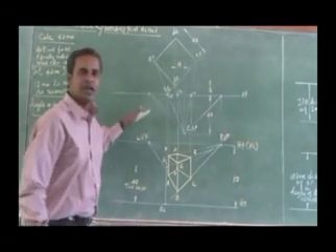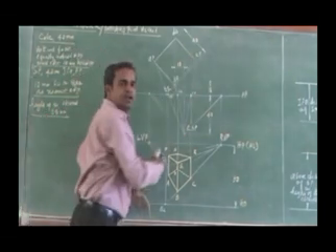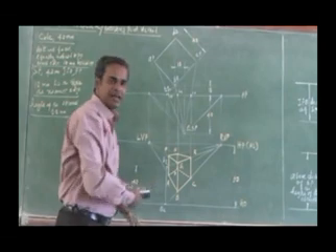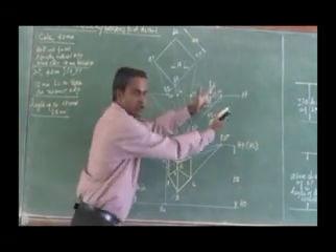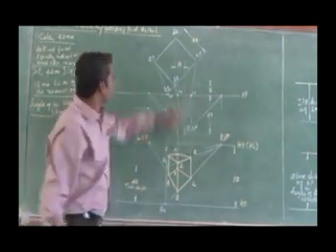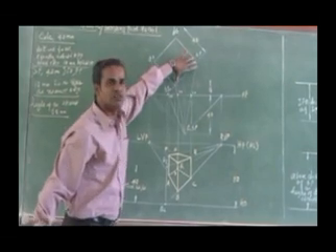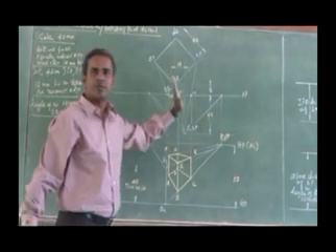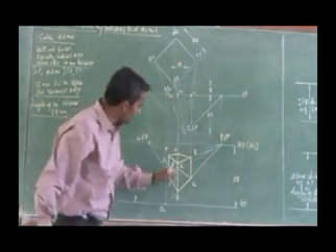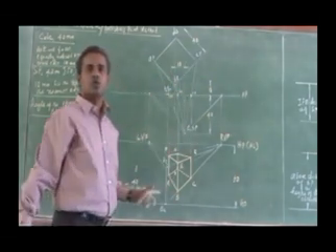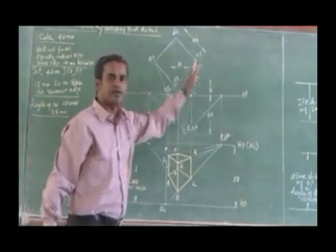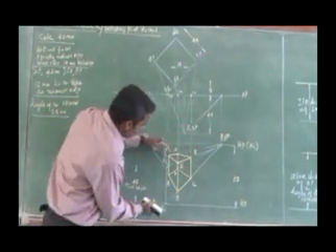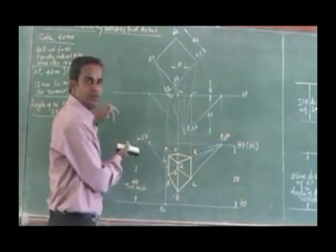Since I have extended to the left side, parallel to the right vanishing line, then that I have joined to the right vanishing point to obtain the perspective of this face BQ and CR. So intercept as usual, previous method I have obtained, I have got the perspective face of this one. Then this face BQ, you should not join B2 Q2 again to left vanishing.